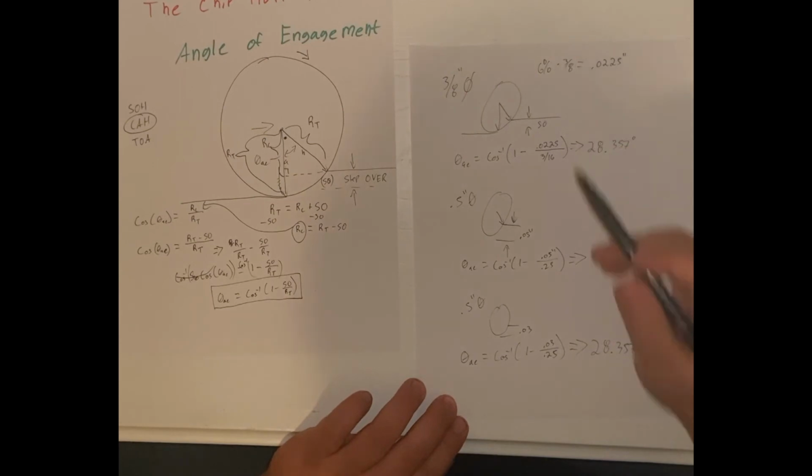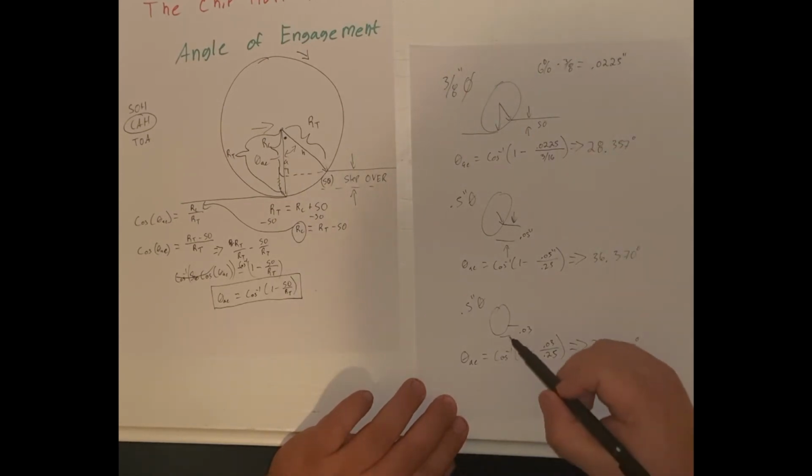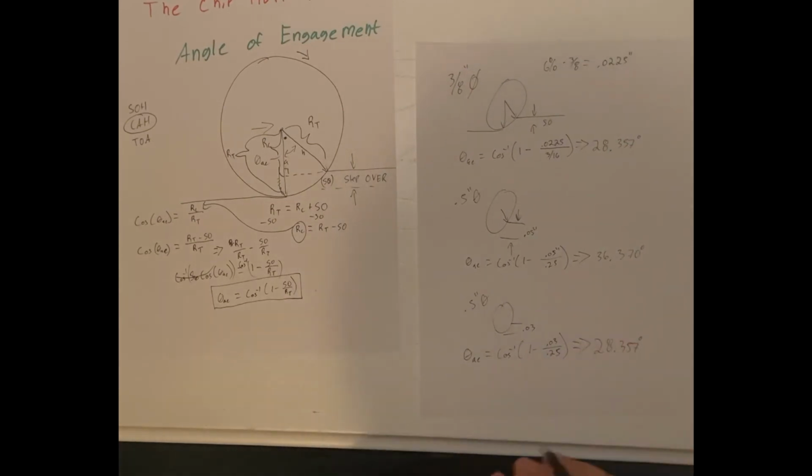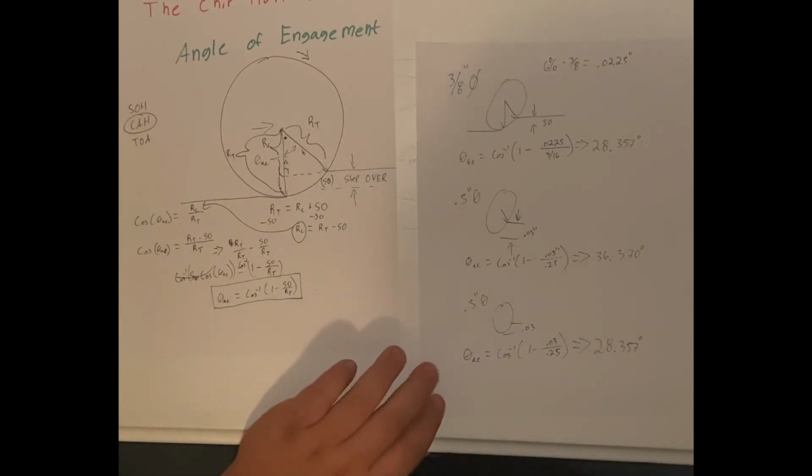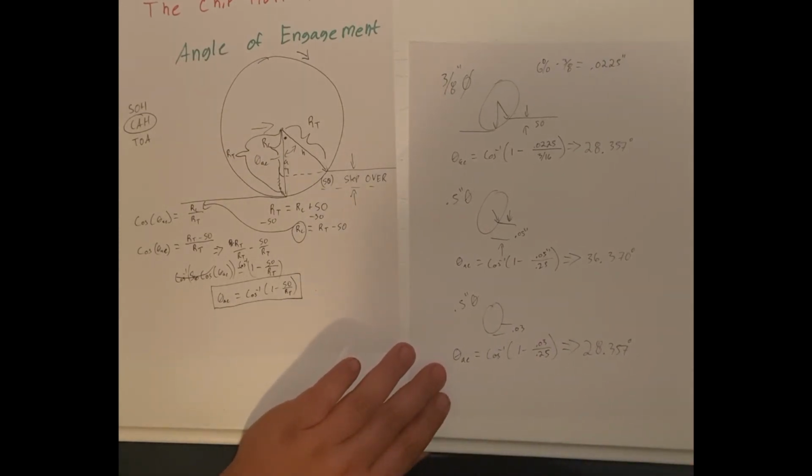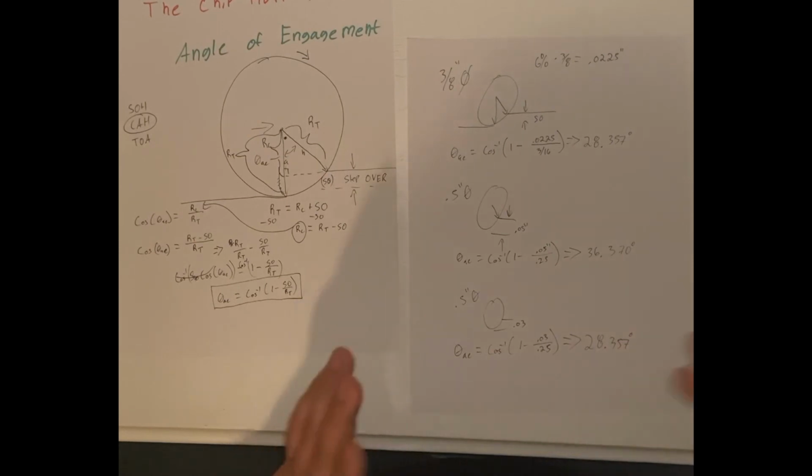So using percentage maintains a constant angle of engagement with different tool sizes. So like I said, that helps you basically maintain and control load, and keep that load with the tool size as you change tool sizes.